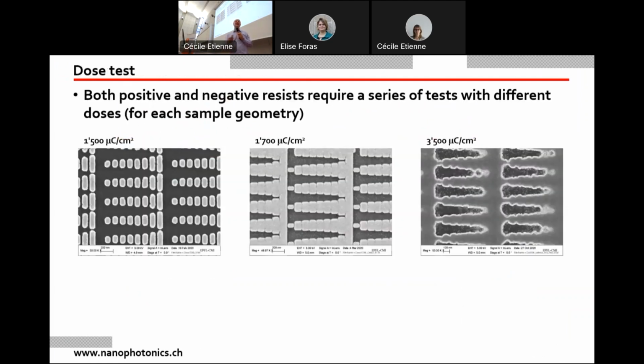Of course, when you do this nanotechnology, there are a lot of steps. Whenever you work with electron beam lithography, it's a very tedious and painful process, to be honest. You first have to calibrate your system. You have to check that the dose you're using, the power, if you want, of your electron beam is sufficient to develop your structure, but not too much to make them too big or even gigantic. So there are a lot of steps that are required before you can really produce something pretty that you would be able to measure.